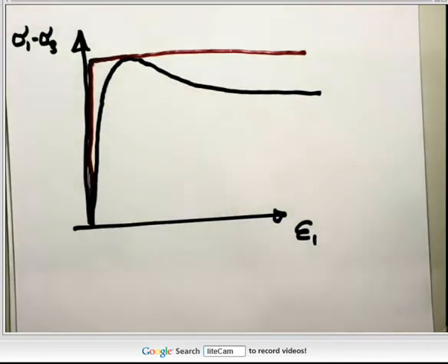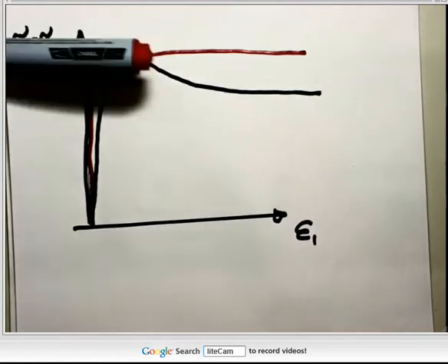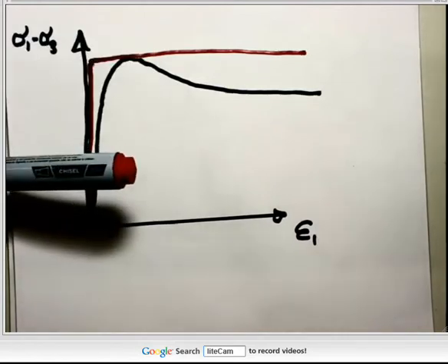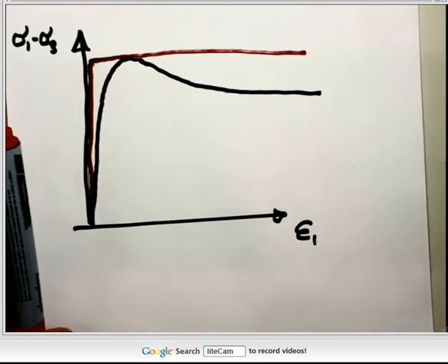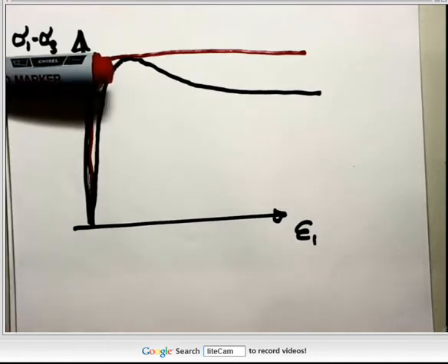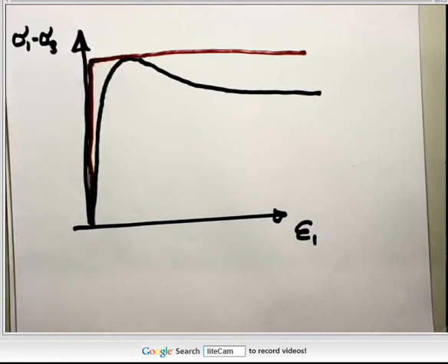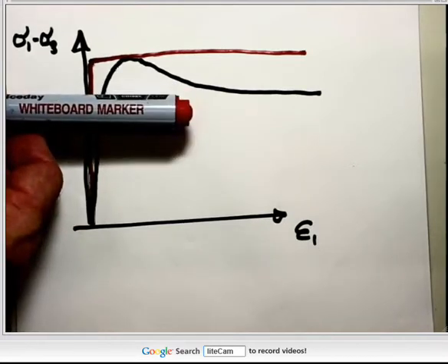What that constant shear stress is, we've got a choice to make whether we use peak strength or constant volume strength. Now, if we assume that displacements around the failure surface don't vary much, so that everywhere is mobilising the same proportion of strength, it's safe to use the peak strength because all the soil will get to peak strength together. If, however, the soil is very compressible, so we push down on the foundation and we get a lot of movement locally, but further away we get no movement, we ought really to use the constant volume strength to avoid the problem of progressive failure.